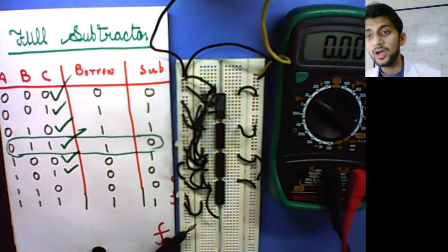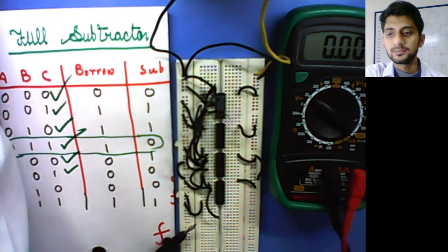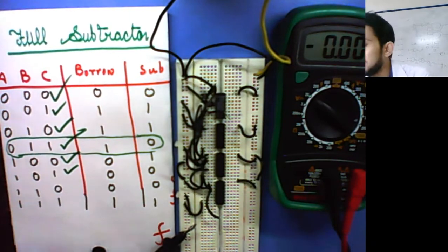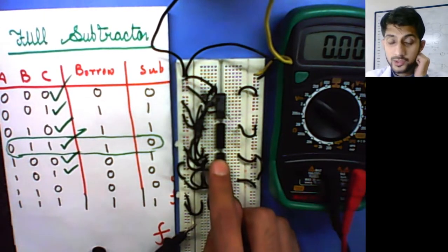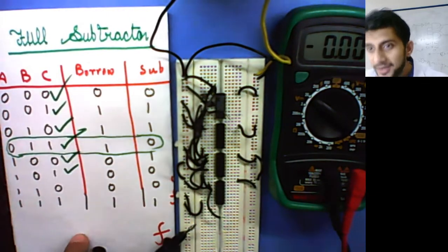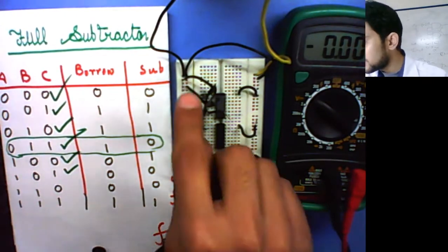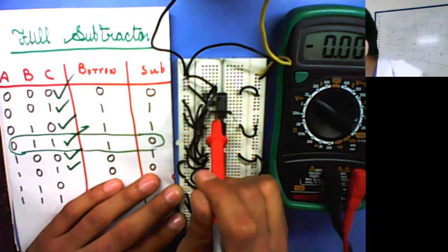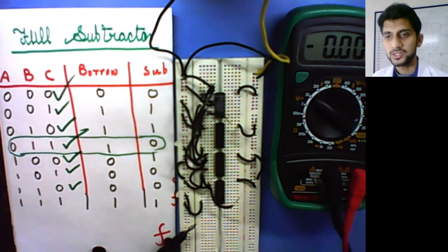This means all the other outputs that were coming were working because that particular portion of the gate was not needed. The ones we verified earlier did not require that IC to be working. But now that we have figured out that this IC is working properly, you should reiterate the whole process and start again from here. I'll skip that for my part because I just have to verify whether for 1, 1 and 0, I'm getting 0 and 0 or not. So I'm getting 0 and 0, so this works fine for me.